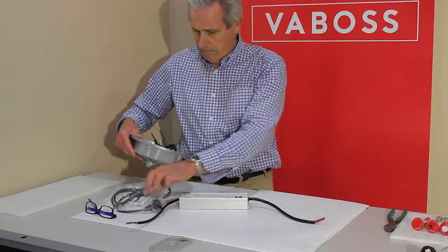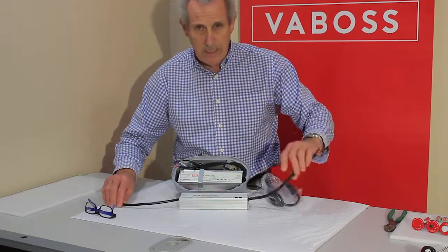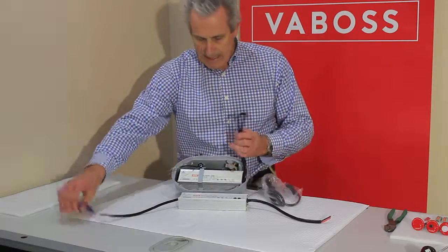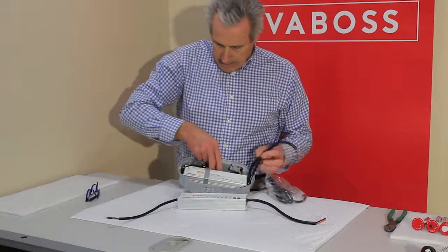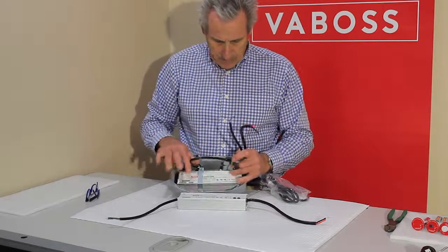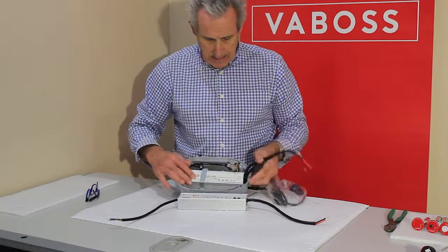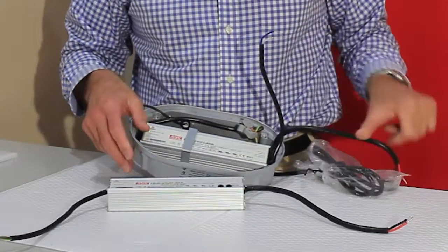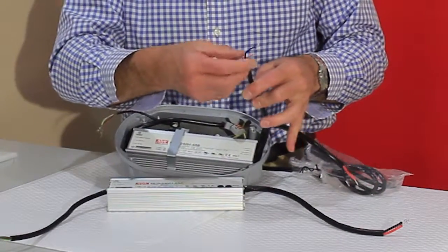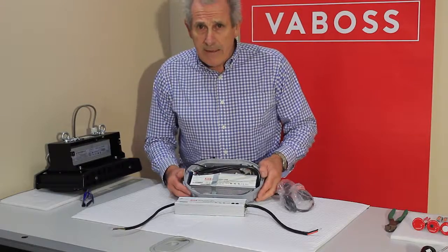There are two types of drivers, standard and dimmable. What's the difference? Well, as we said before, power in, power out, just two leads, whereas the dimmable one has an extra lead on this end. So this is the power lead in. In fact, its power comes through here, through these blocks, in here and out this end. So there's the same lead as that one. This is the control lead. This is positive and negative control. That's the difference.